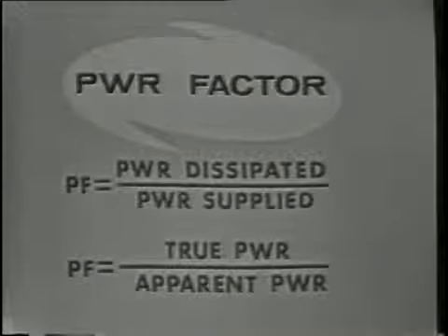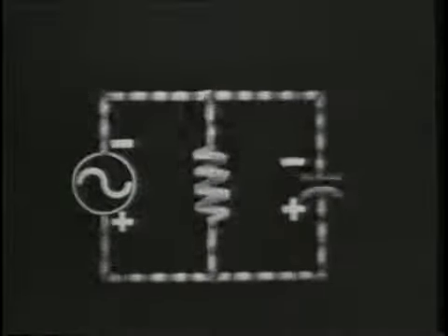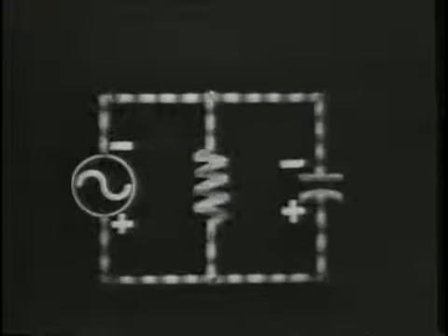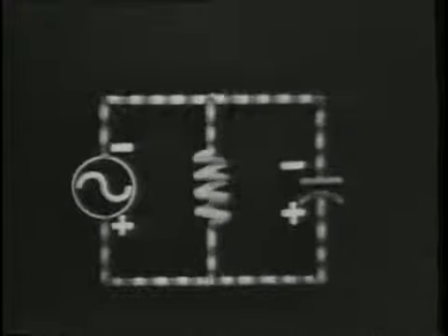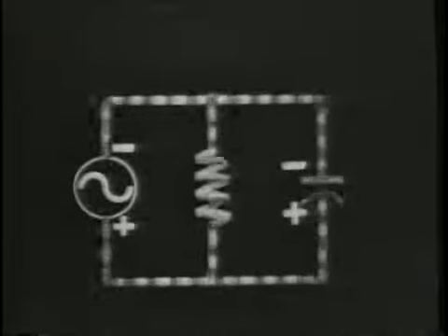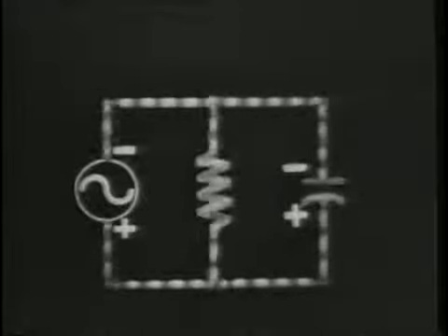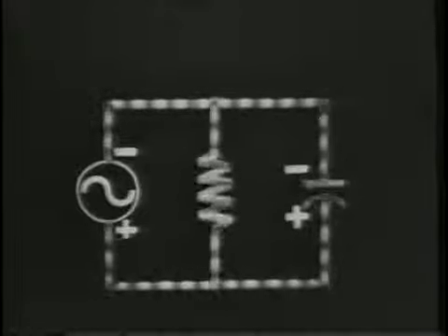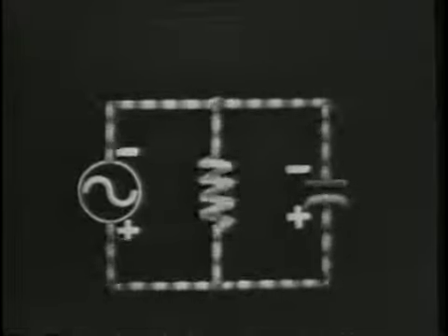Now, this point may be understood by looking at our circuit in operation. When the first alternation occurs, current flows through the resistor and heat is generated, or we dissipate power. Current also flows to the capacitor, but the energy is stored in the capacitor and not dissipated.